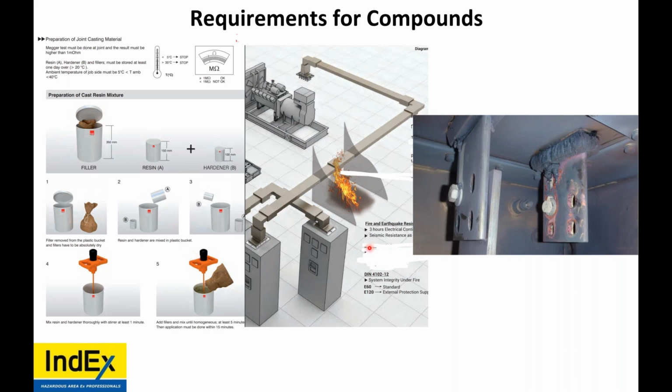Now, on the end, inside the transformer, you'll find the terminations. Now, this box is Ex e. Unfortunately, somebody ran this one for 4 months with only 1 bolt on the flexible bus links, and then it blew up. So the problem is, when it blew up, this entire section had to be replaced. You're talking millions of dollars.